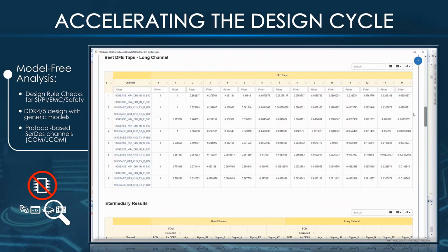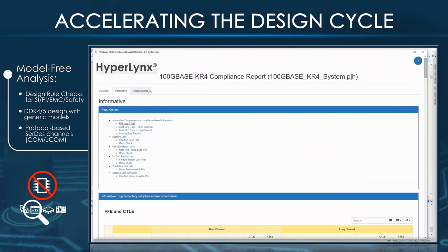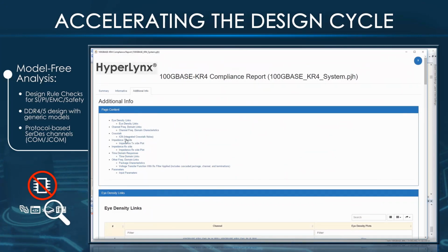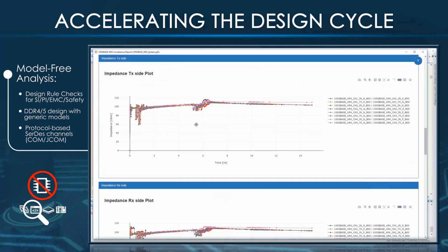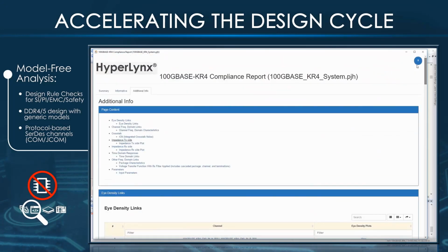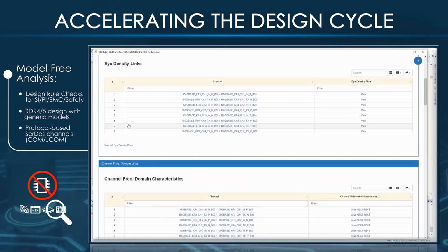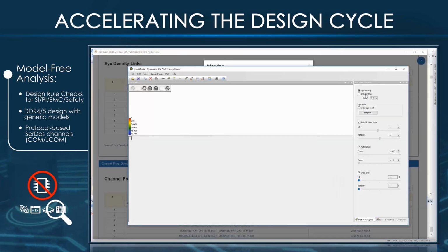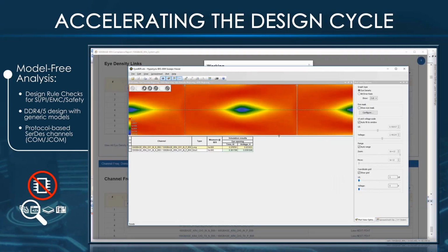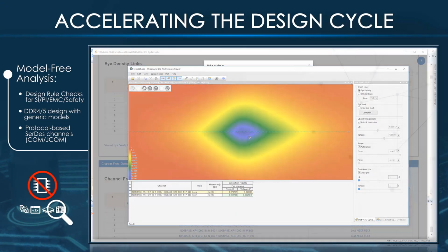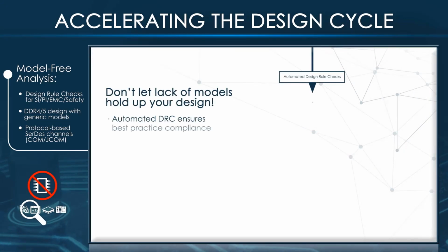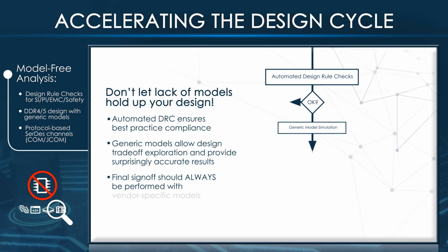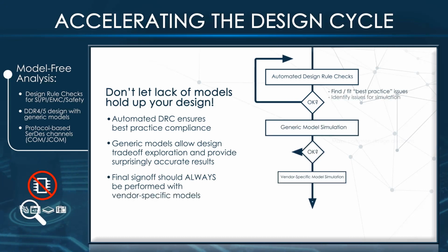And here we can see a little bit worse results than before, if you remember those results from before. And you can even see it in the impedance plot there. I have some really strong dips, probably due to some excessive via capacitance. And so if we look at the eye diagram, again, strictly qualitative, but you can see that there was a big difference with the eye diagram that we ran before.